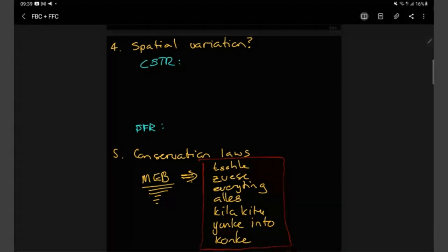So that is a very important thing just to consider, and that kind of comes from your assumptions. So if you don't make the assumption of CSTR, then obviously you must include some form of spatial variation in your equations, which complicates the model a lot. So when we are considering something that could be considered as a CSTR and you don't make that assumption, you've already crossed that boundary of too complex, and you should probably just revisit the first couple of points in this table.